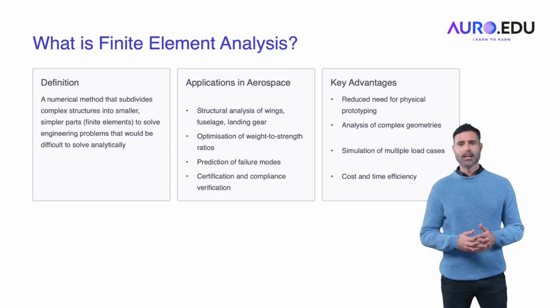What is finite element analysis, FEA? Finite element analysis, FEA, is a numerical method used to solve engineering problems by subdividing complex structures into smaller, manageable parts known as finite elements. In FEA, the continuous structure is discretized into elements, each represented by a set of equations. These equations describe how the structure behaves under various forces. FEA is used to analyze everything from aerodynamic forces on wings to structural stresses in fuselages, allowing engineers to predict how the structure will perform without physical testing.